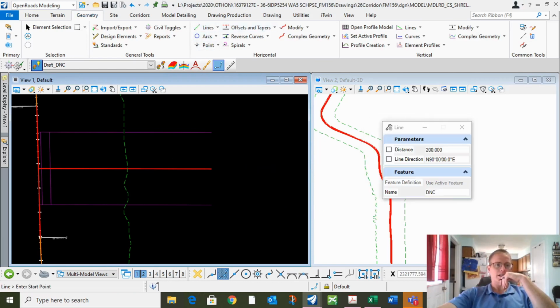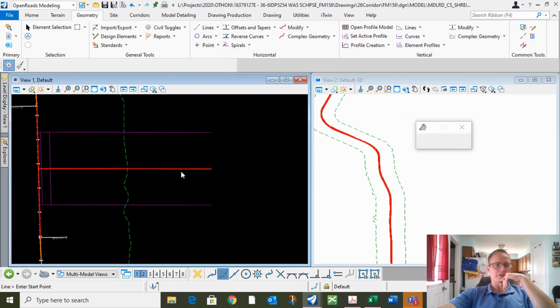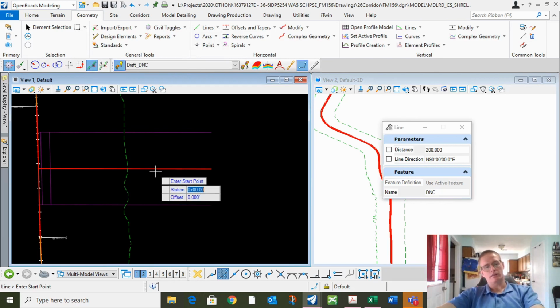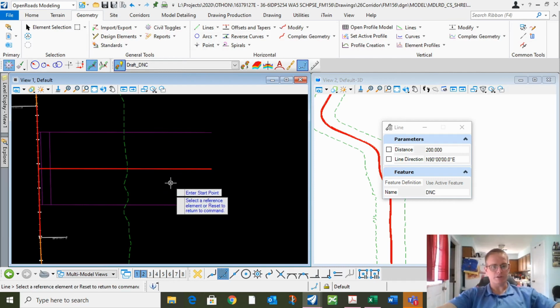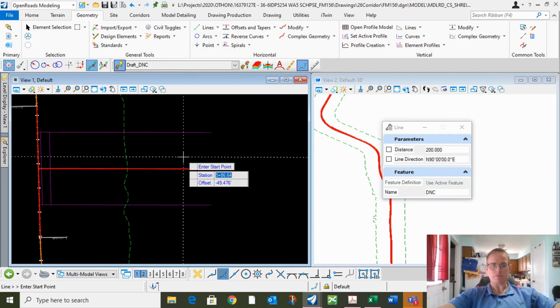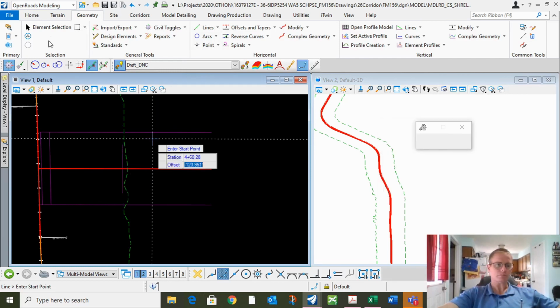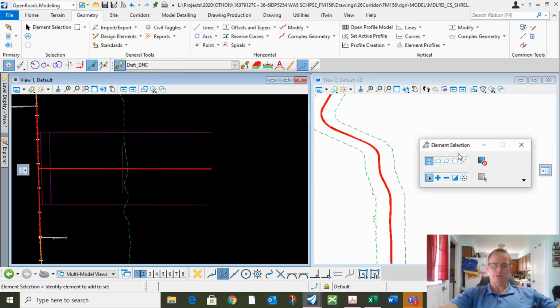And so we'll create a line, turn on Civil Accudraw, which allows us to do a station and offset. It's asking for a station and offset, but it doesn't have any reference, so you need to hit the letter O on your keyboard, and it'll ask you for what element you want to reference off of. So now we'll put in station 340, and we'll do an offset of 100, and do that again. 340, offset 100. Excuse me. All right, now we're starting to get some elements.